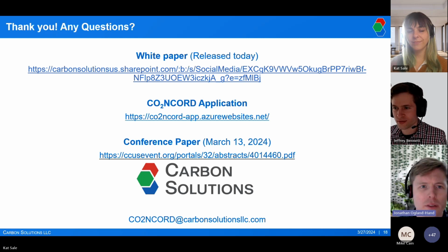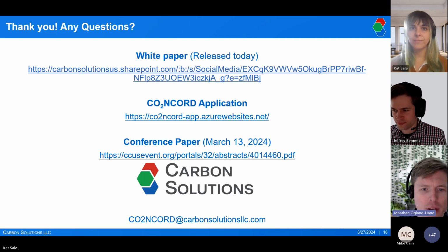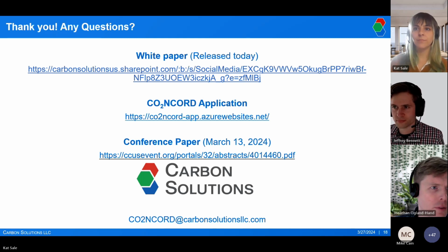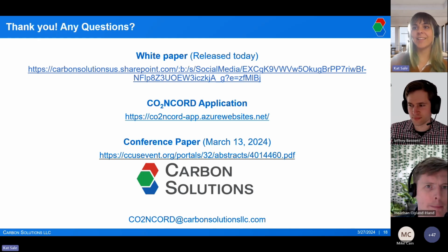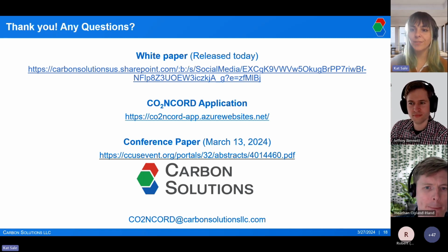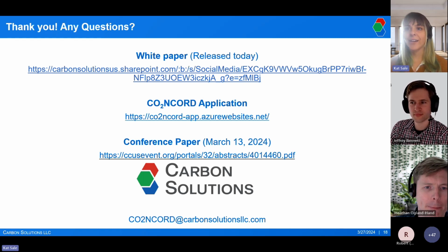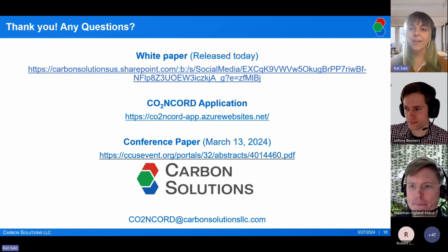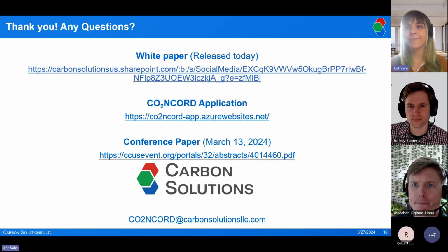All right. Thanks, Kat and Jeff, for the awesome presentation. A couple questions in the chat right now. First, what do you mean by high purity CO2 sources from oil and gas production? I could take that one. So from oil and gas production, sometimes you have acid gas removal streams. And so in that area, you may have a nearly pure CO2 stream that can be removed essentially with only the compression equipment.